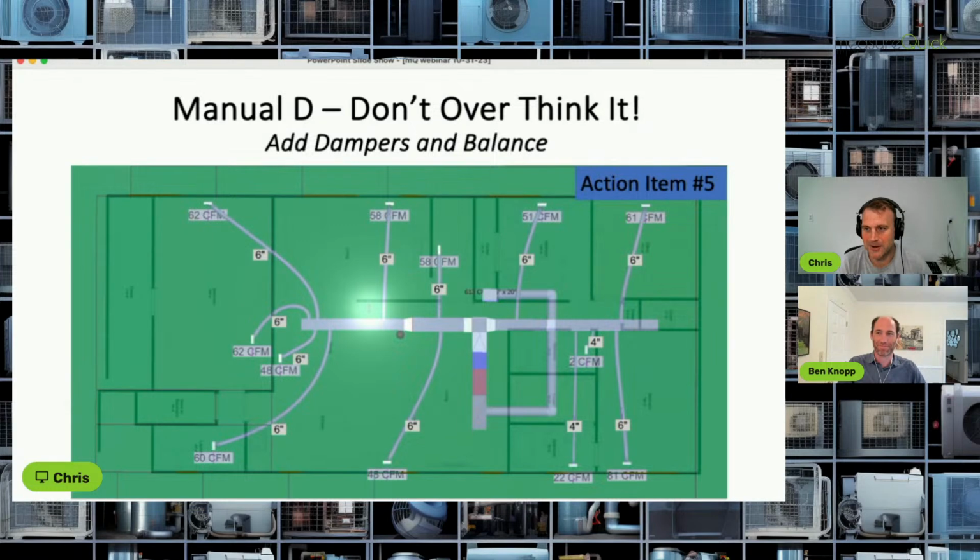So what I wanted to know is, because this is a weatherization project, we're trying to save money where we can. That's a lot of square duct, and I don't want to replace it all if I don't have to. So I ran a TrueFlow from the back of the unit, and I captured supply static when I did that, and I think I got around 1100 CFM with a supply static of like 0.1, which told me, well, if I know I'm going to reduce my flow, I know I'm going to reduce my static, and my ductwork's in an encapsulated crawl that's going to be basically conditioned. So I don't have to worry about duct sweating, which means the supply trunk can stay, right? So it's a win-win.